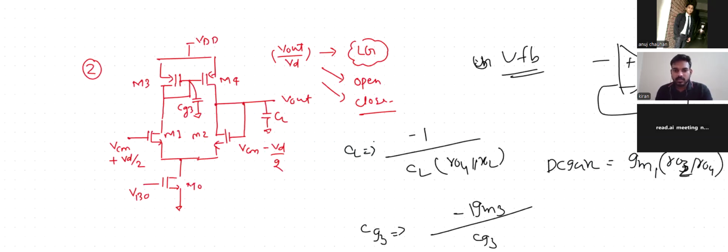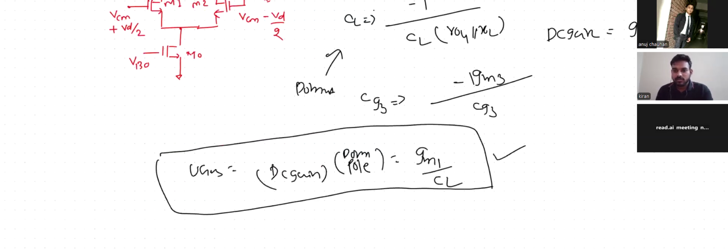So I can say UGB will be the DC gain times the first dominant pole. This is my UGB. What is the UGB? Gm1 by CL.